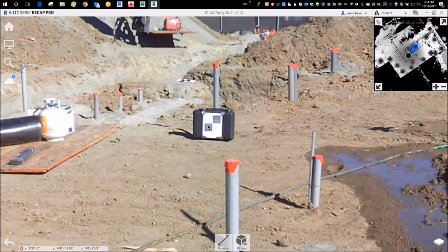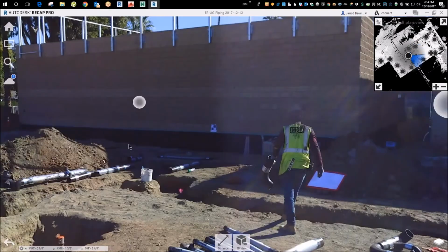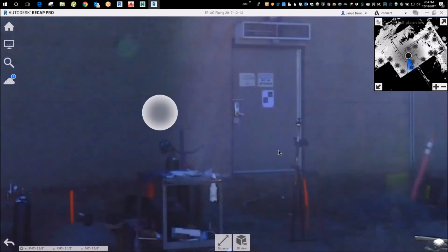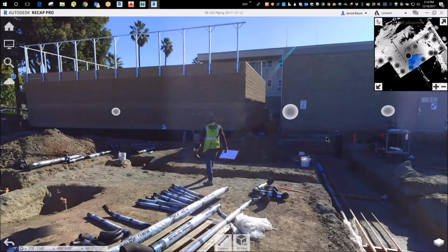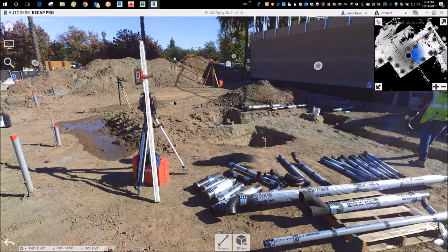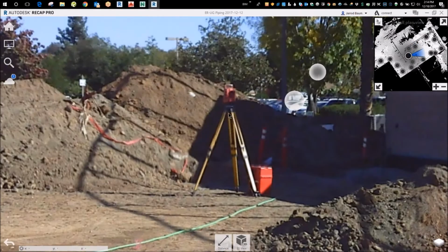So you notice that right there? That is a target that's designed to be detected by the software of the Faro scanner. It basically looks like almost a nuclear waste symbol, but you notice we have 1, 2 on that wall, 3 of them. Those are needed for either A, precise registration of point clouds, and B, you notice our total station, I guess it wasn't set up on the hill yet, but there's the plumber's total station.